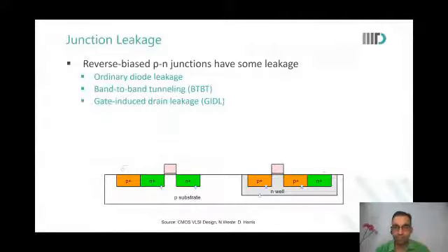But how are we connecting the different P wells? I mean, how would we be connecting the different P wells of our NMOSs? Just look at this photo. If I make any more devices in the same P well, P substrate region, it is the common P substrate region, is it not? They're naturally connected. Sorry, sir. So actually, I was asking about the N well kind of thing. I was thinking about even N wells. If you are biasing all the N wells to the same value, and all N wells are then connected.